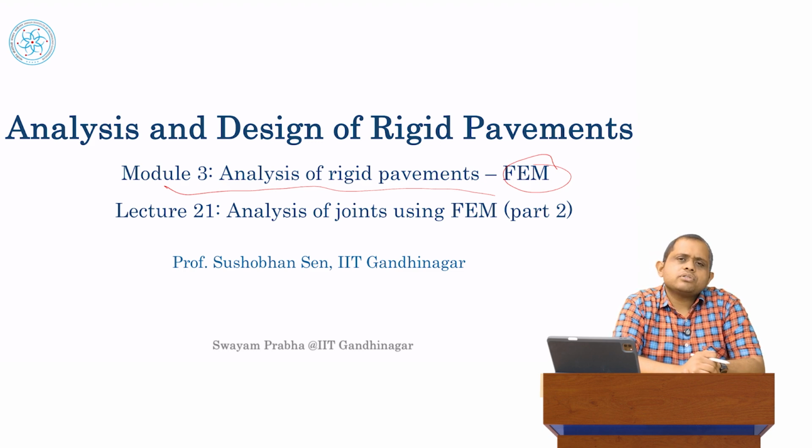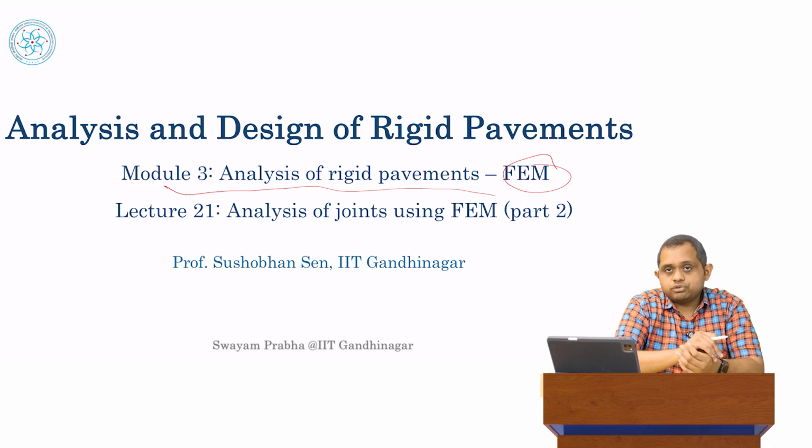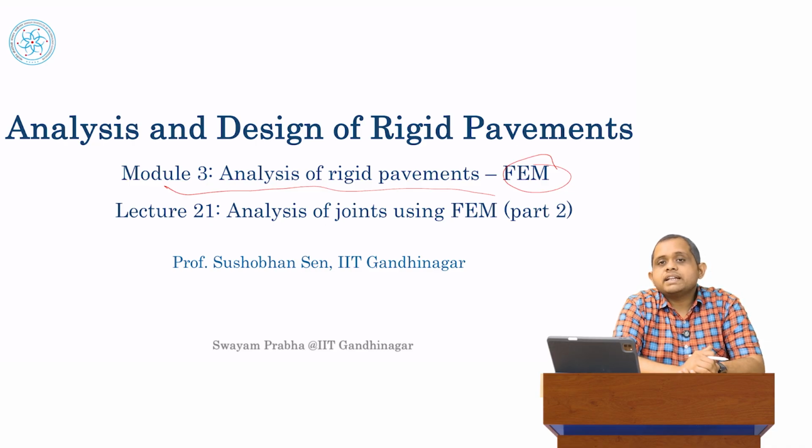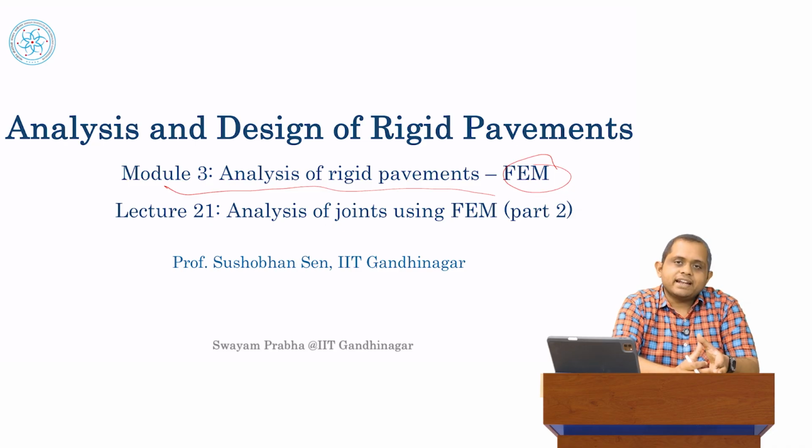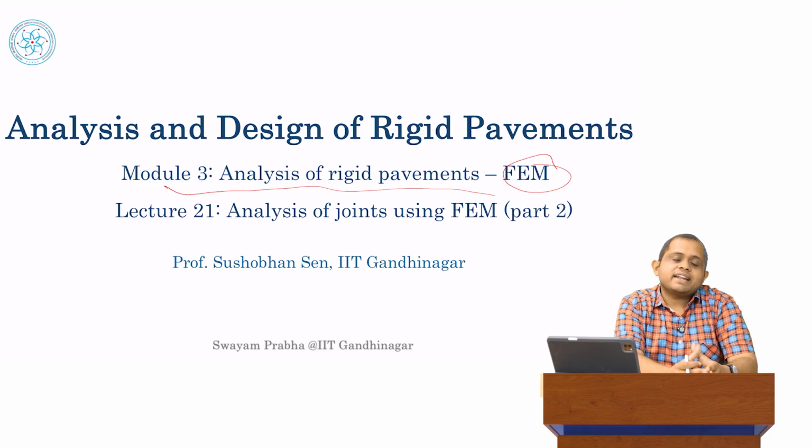The basic assumption of the finite element method is basically two assumptions. One is we are no longer interested in solving the solution everywhere. That is, we don't want a continuous solution. We are only interested in getting the solution of the system at a discrete set of points, which we call nodes. And the nodes themselves are connected to each other using elements. So if we have a finite set of points, we have a finite number of elements, and hence the name finite element method.